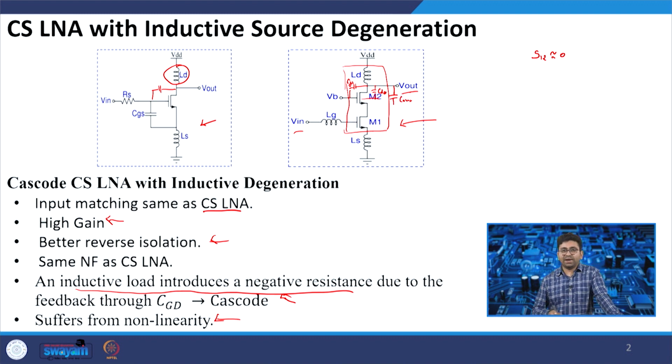Because when we are designing a low noise amplifier on chip, the next stage might be the mixer or any other filter that we have designed. So, mostly on chip the next stage will be a mixer, or a buffer if you are keeping a buffer in between, and your LNA should drive that much capacitance of the next stage.